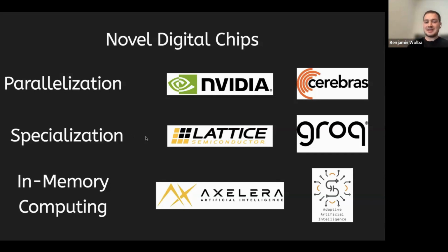So all of that is still sort of the same familiar computer architecture, which is called the von Neumann architecture, which basically has a separation of memory and processor, and you're shoving data back and forth. And while this was very convenient to design computers, it has become a bottleneck because memory is typically way slower than your processor, which means the actual bottleneck for most of AI compute today is memory and bandwidth to get data from memory into your processor. Now, what you could do about this is in-memory computing, pretty much doing computations within your memory. So you're still digital, but you're computing within your memory.